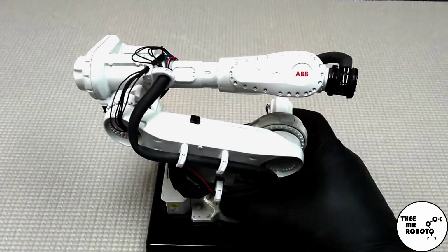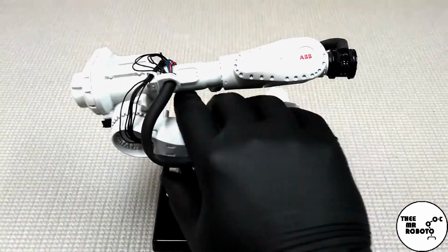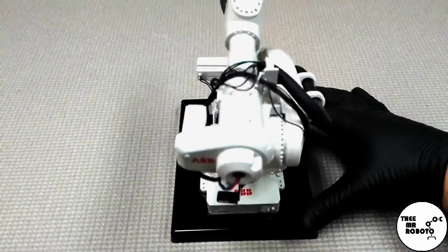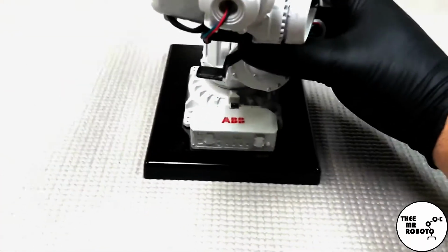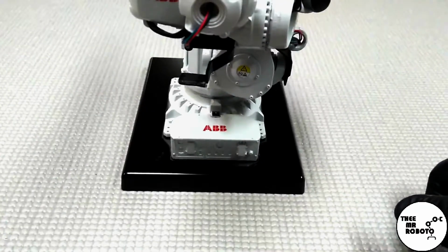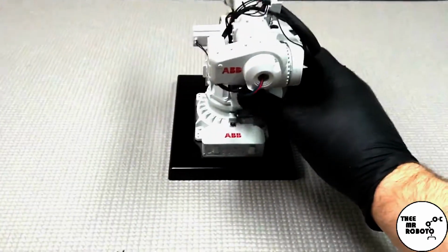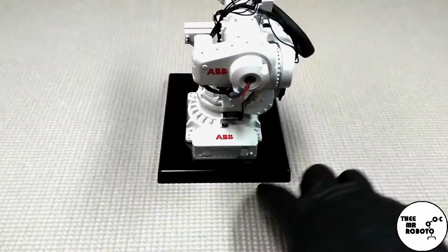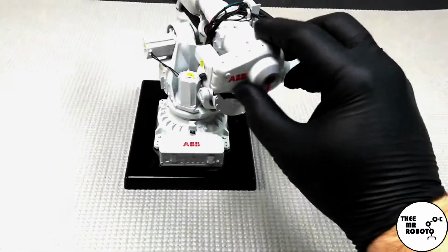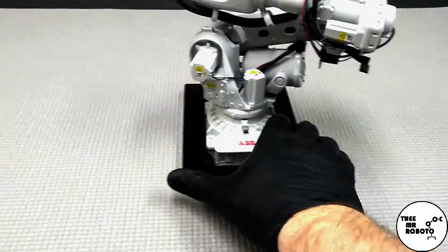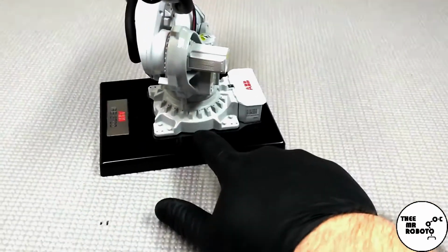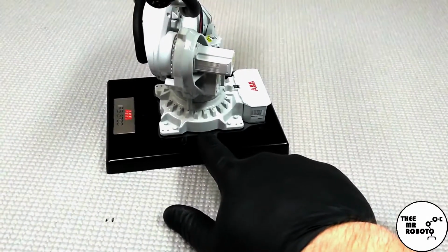So the two I'll start with. The first one is what sometimes is referred to as a world coordinate system. Okay, so if you look at the back of the robot, all right, again, the back is usually where the cables are at. The world coordinate system is usually center line on this axis, okay? And also center line in this direction and on the bottom of the base.